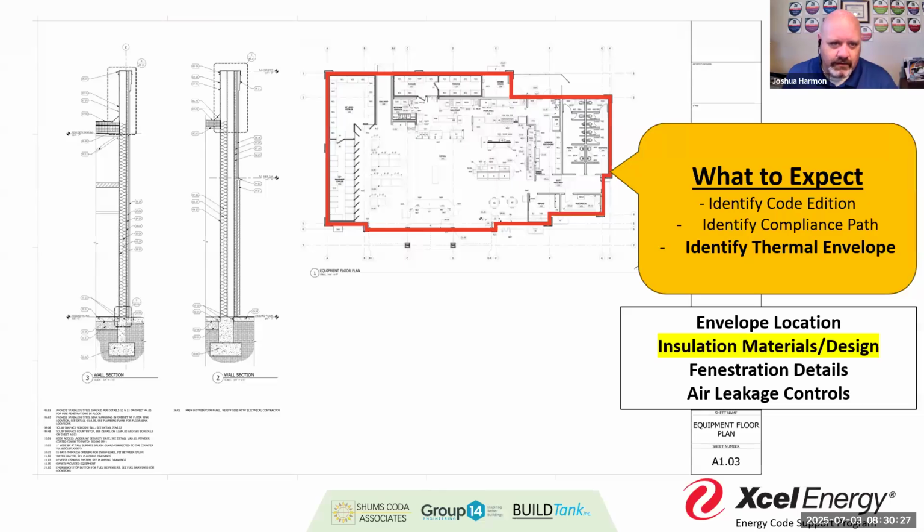These are the CDs. A separate sheet indicates a lot of this is covered in specific details. And I find a lot of that information is also going to be in the spec sheets. One of the things I like to see though is a call out, a record, even if it's a note, right? I read through all those detail sheets all the time, and it's a great place. And I like to see where we've called it out and recognized it. Now, one of the things I get a lot of too is all insulation shall be part of the thermal envelope.